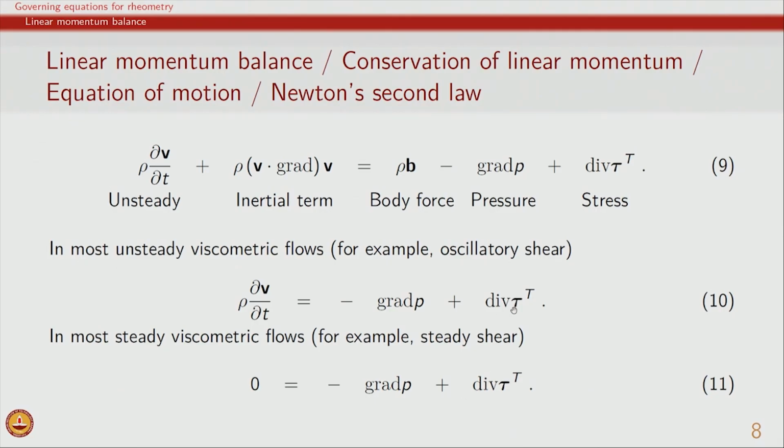We remind ourselves that we do not really know in some cases how the fluid stress depends on various kinematical quantities such as strain and strain rates, and in fact the purpose of doing rheological analysis and characterization using a rheometer is to first try to observe how some of the properties change as a function of strain, strain rate and other kinematical variables.